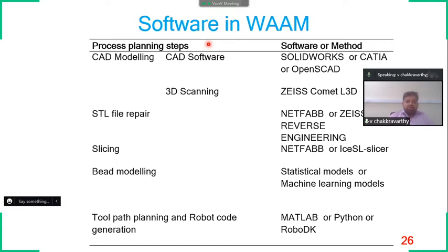So we can go for general CAD modeling techniques like SolidWorks, CATIA, or anything to construct a geometry, if we don't have that white light 3D scanner. We can use these CAD modeling tools to generate a geometry. And once we prepare an STL file, that will be given as an input to the robot. So based on which the robot will be fabricating the component, or the CNC will be fabricating the component based on the geometrical codes.